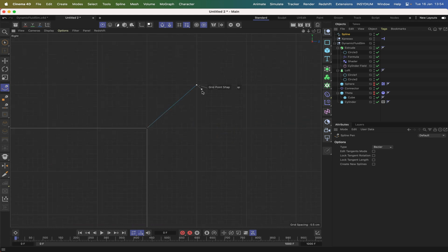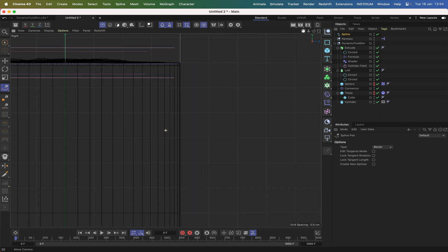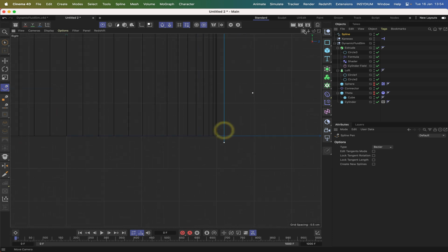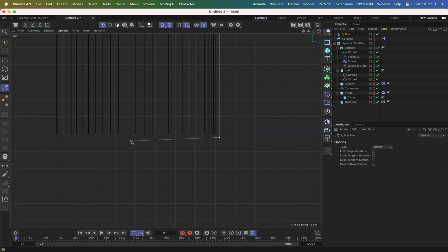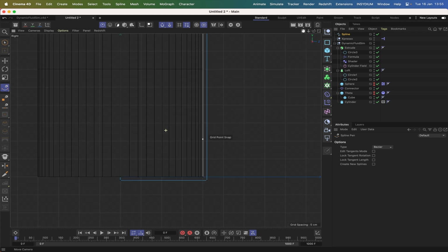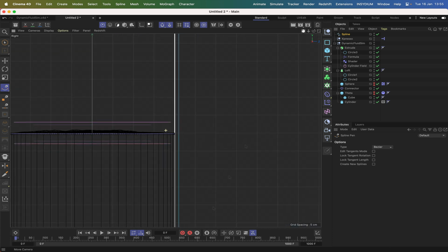Just see where we are. And we want to come to somewhere around here. We don't want the glass to be too thick. Something like this should be okay, I would think. And then we can come down to the bottom again, drop this down, say somewhere here, and then once again we've got to head towards the middle of the beaker, which is just here where the line is there, and then that should be it. We should be okay. If I just hit escape, I should have a full profile of that spline. Let's just see if we have. I hope we have.